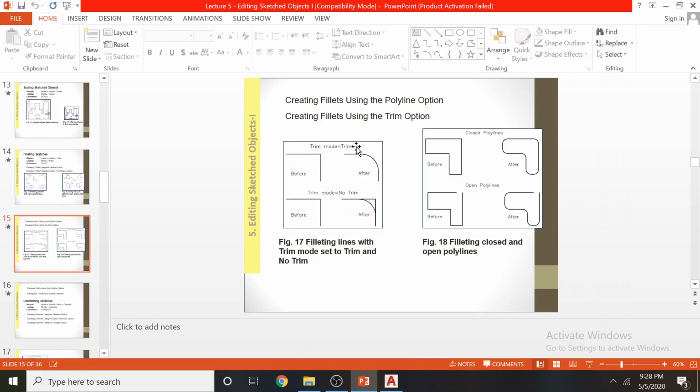When you make it a round corner, the stress is going to be reduced. We are going to give more area here. When you give more area and a force is applied to this area, the stress levels will be reduced and there won't be any cracks forming here.